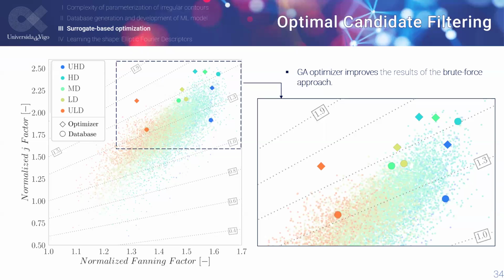So first, if I were to do it at the beginning, I would use adaptive sampling to guide which parts of your search space are more useful to be running, for example, expensive simulations to improve the accuracy of your results. Now, if I would have the ability to build any of these fins, I would do so with the fins that are the optima, just to triple check. So basically I have the optima with my genetic algorithm, I double check with my numerical solver, then I print them and I see if there's a correspondence in between.